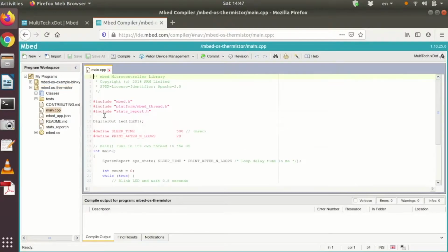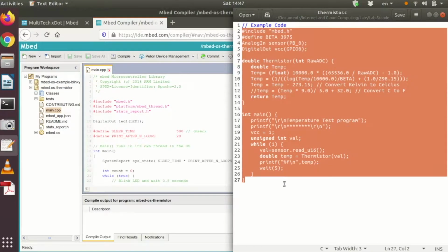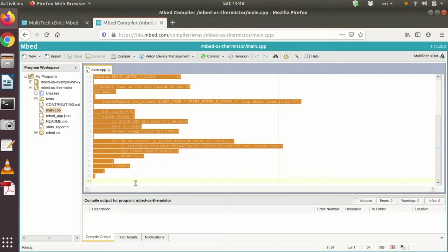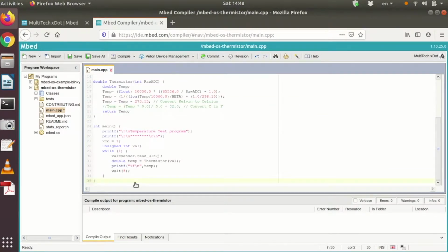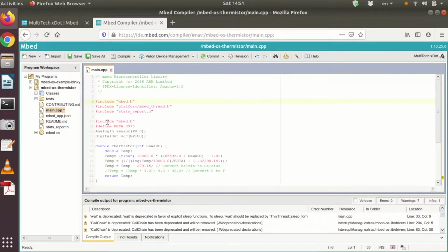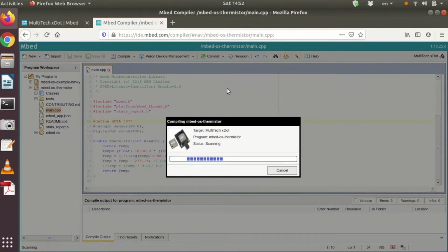The GPIO 0 and ground pins in the xDot are used as source, while the GPIO 2 pin in the xDot is used to get the output values. Here, we use the reference provided in the lab. Then, we will compile the program and repeat the process of pasting the executable output to the xDot folder.